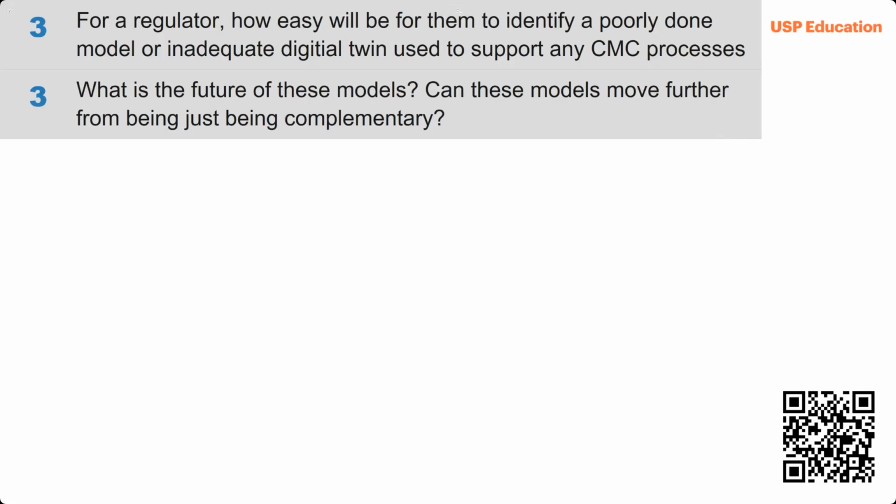If you are using the model for process control, it would become a high impact model versus a low impact model for process development. That would go to CPV, or continued process verification, for model maintenance. So answering your question, it depends on what kind of model you are developing and what the application of the model will be.